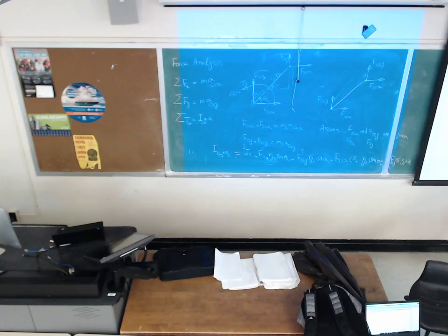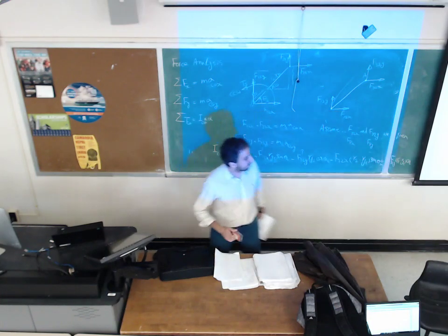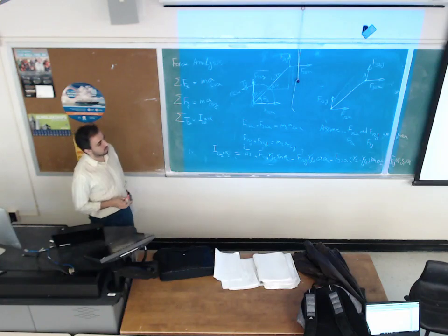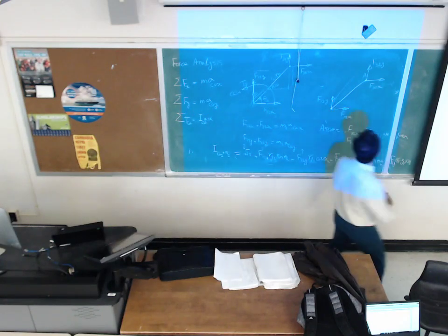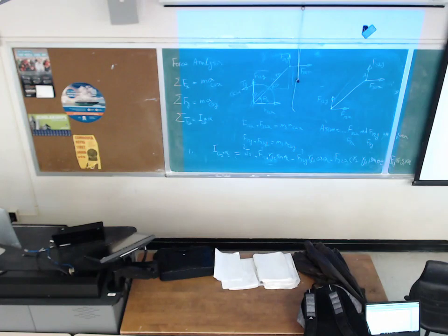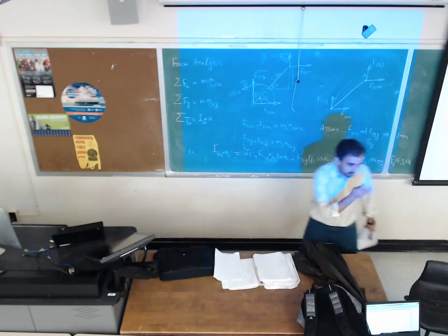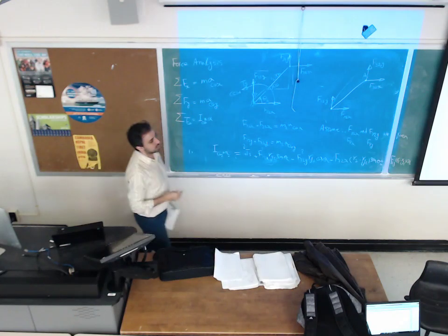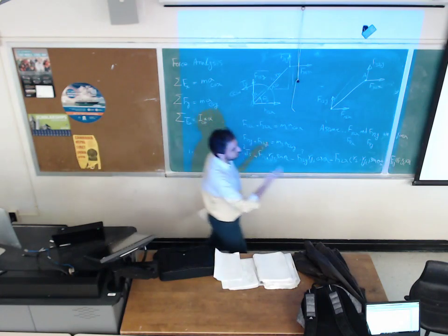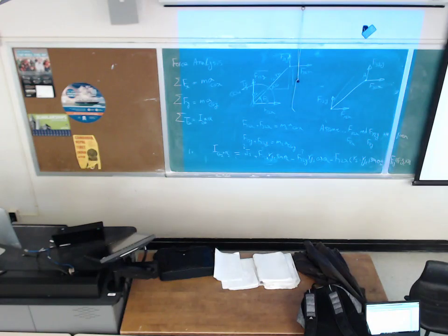On that homework, I'm asking you to find the angle at which we need the maximum torque. Then you have to do the force analysis for all 360 degrees and just look at the curve to see where the input angle is at which the maximum torque is needed. Or if you are looking for the maximum force applied to link 2, you can find that angle. Okay, let's go back to this example.